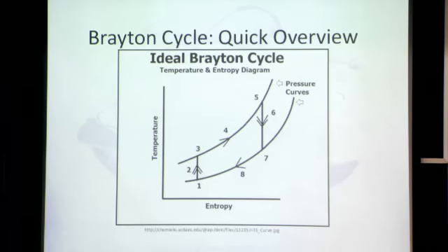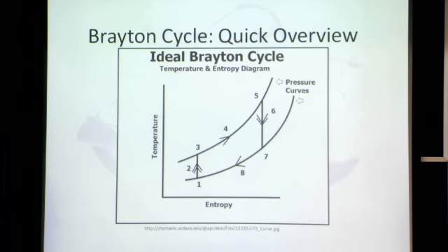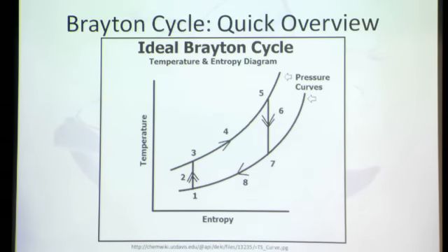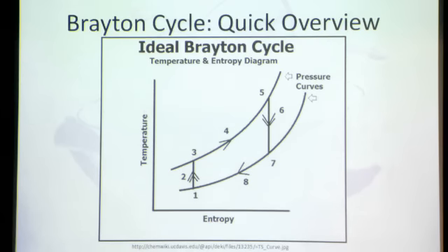I'm just going to go over quickly that we're using a Brayton cycle instead of the traditional Rankine cycle that you'd find in a PWR, BWR. This consists of 4 steps: an isentropic compression, then isobaric heat addition, isentropic expansion, and then isobaric heat removal.